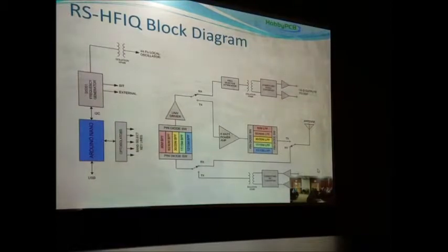So there's a lot of flexibility there with that clock generator. Now on the right-hand side of the drawing, all the switches are shown in receive. So I'll start there. The signal from the antenna gets routed to the bank of bandpass filters. There's 5 of them, and they're switched in with pin diodes. Out of that, it goes into the LNA, which also doubles as a driver in transmit.